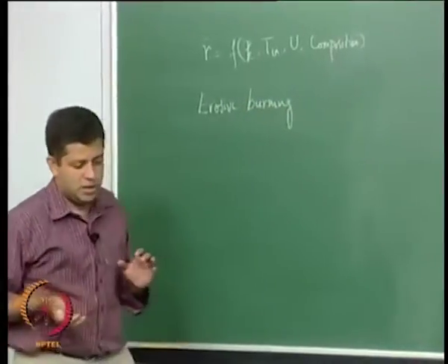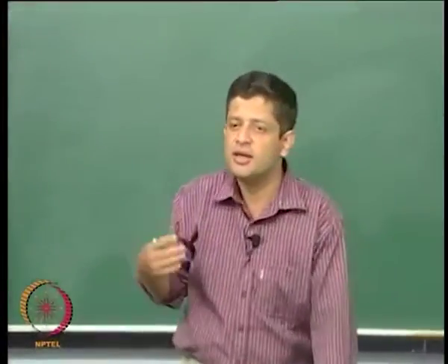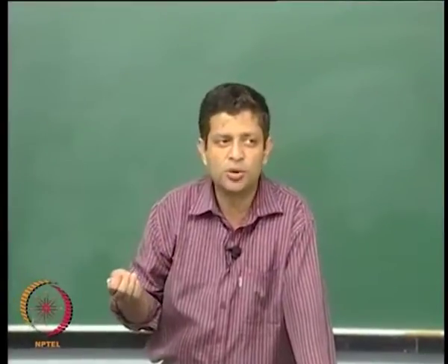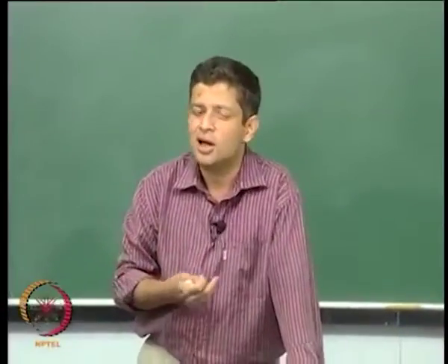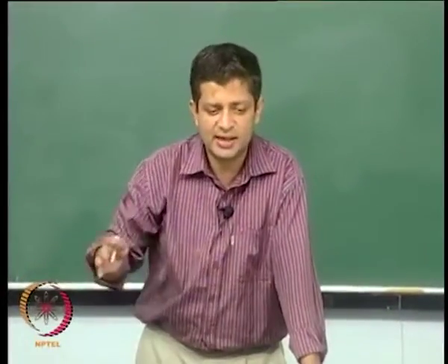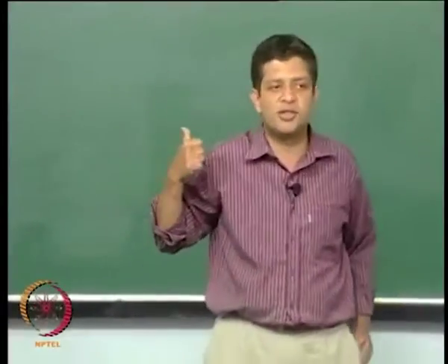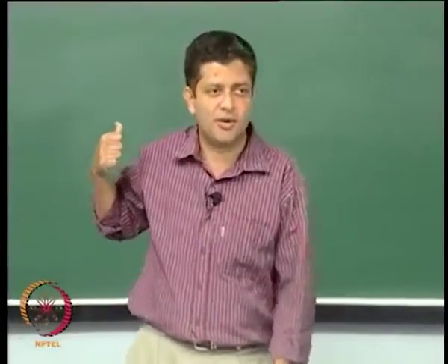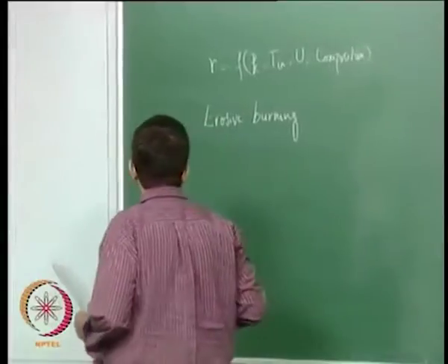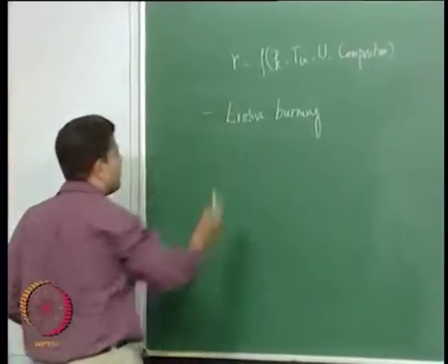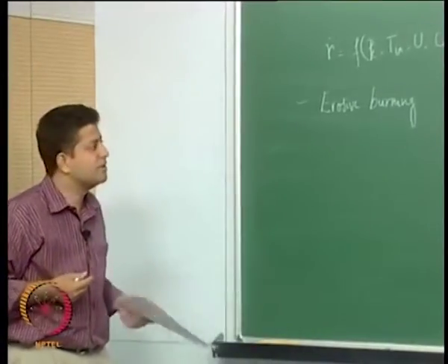That is, if you have a rocket motor whose port diameter is quite close to the throat diameter, then it is going to be subjected to erosive burning. We will discuss that a little later in the course. So this is one part we will not be able to measure in our strand burner tests. So the first thing that we are not able to look at in a strand burner test is erosive burning. That is going to be different in an actual motor compared to this.